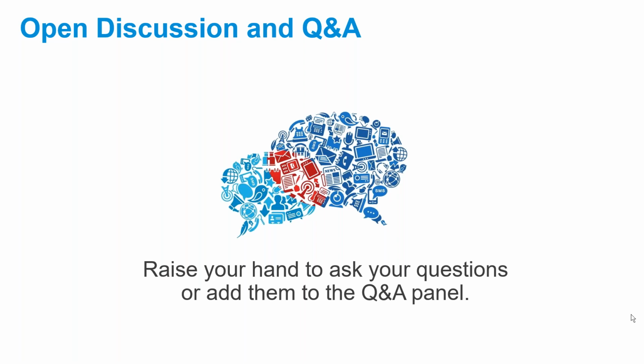Last question here is, what information is out there for BIM 360 interactivity with Plant 3D and Navisworks? So I think there might be some information around the new issue tracking, where you can actually flag an issue in BIM 360 and then synchronize and see that on the Navisworks desktop. That's the main integration I've seen so far. And I don't know if that's in an article or maybe a video, we could dig that up. Exactly. Yeah, you could do that in BIM 360 Docs, where you can view and assign issues there inside of the viewer,